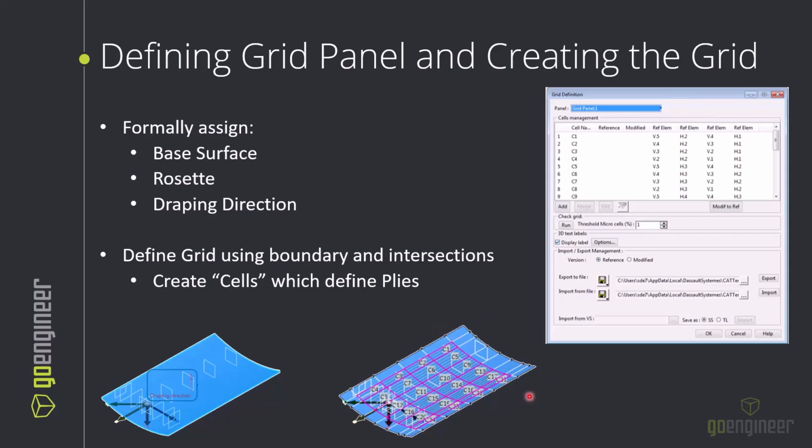Inherently, these cells are developed inside our grid. And at this point, we're taking each cell and assigning a material and fiber direction to it. And then on each specific cell, we're defining how the stack up looks for each cell. So on top of one material and fiber direction, we're assigning another different material and fiber direction, and we continue that process.